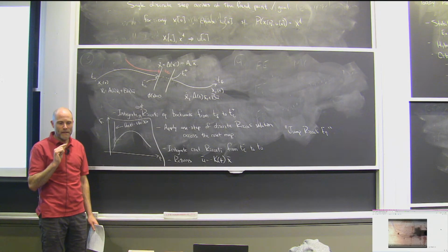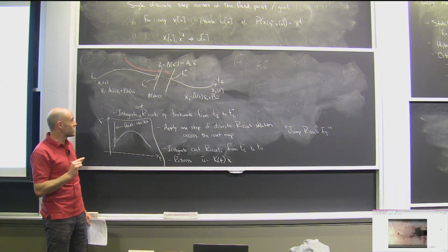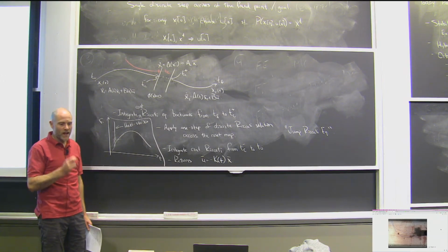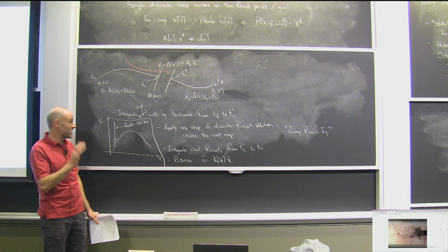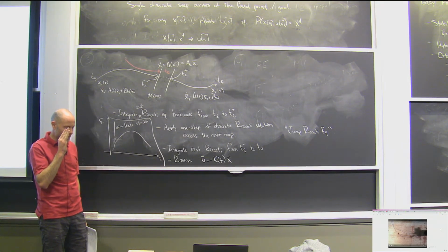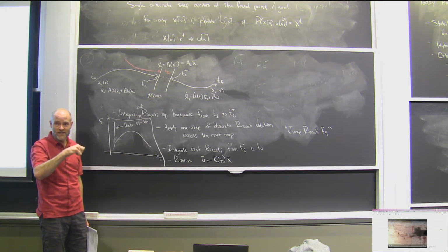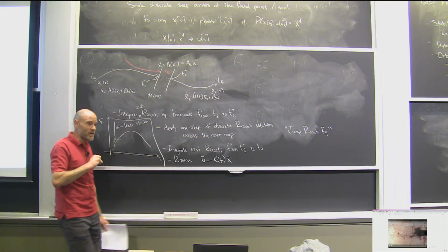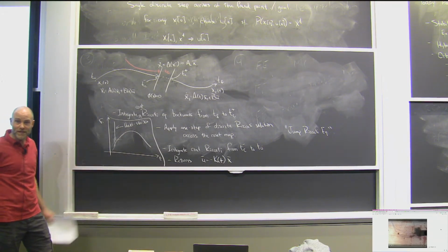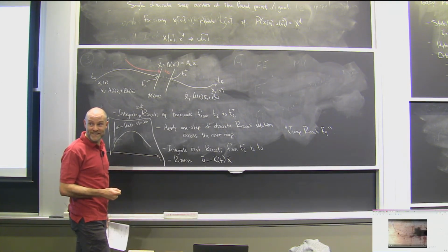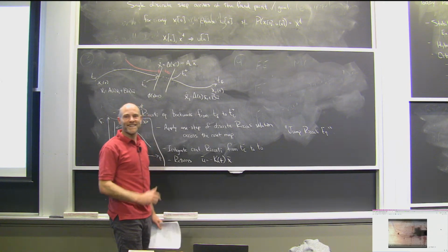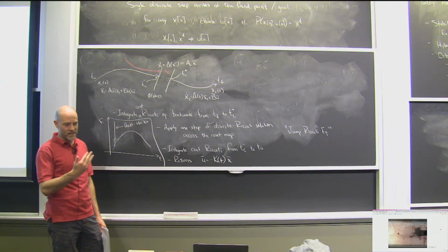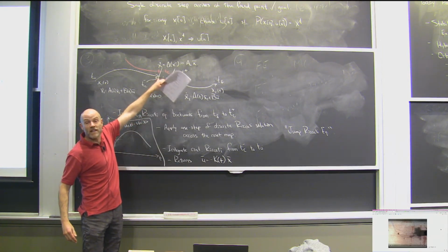Like, for many years, and maybe still today, you can ask the people that have been playing with Mini Cheetah and the like, we would actually turn our control gains artificially down towards 0 right around the moment of impact. It's like this dirty little secret in all of our papers, right? So we'd have our robot, we'd have this beautifully designed controller, it was optimal, whatever, and we kind of turn it off right when the foot's going to hit the ground, and then we wait a second and we turn it back on, and that's all good. See, no, you didn't see anything, right? And it was because of these kind of details.